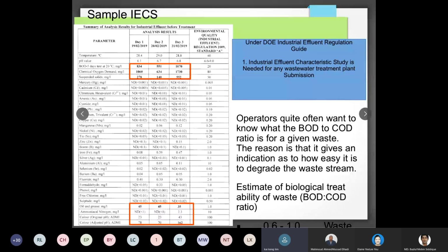So firstly, if you look at this industrial effluent's characteristic, you realize that none of the heavy metal is there. So what we need to focus on is actually COD and BOD. There's some oil, and we believe this oil was not coming from the egg or chicken dung. It is actually coming from the machine which classifies the eggs. So this oil, I would say, is more machinery oil. It's not the oil or the fat coming from the egg itself.